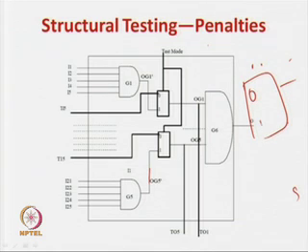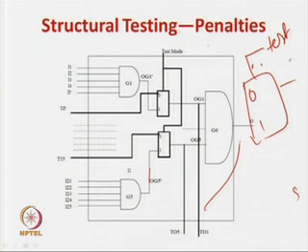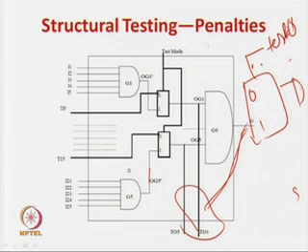So the basic architecture is something like this. In this case 0 and 1 is called the test mode. When the circuit is not in test mode, that is in normal operation, the normal net which is to be feeding is connected, so it feeds there. But when you make the test mode equal to 0, when you want to do the testing, this normal cloud or normal combinational logic which is feeding this gate gets decoupled, and there is a separate pin out, which you can call the test pin, that gets connected to this gate which is driving it, and you can apply test patterns to test the circuit directly. So this is called controllability.